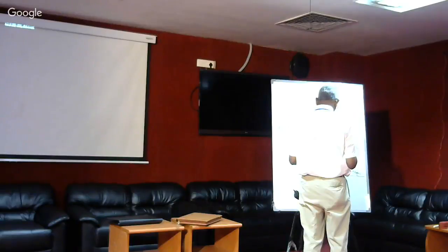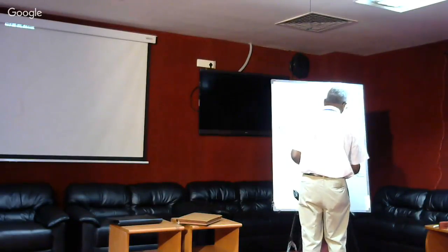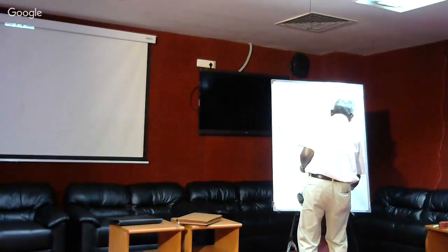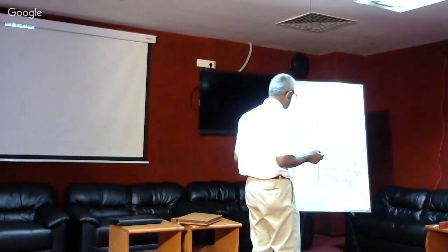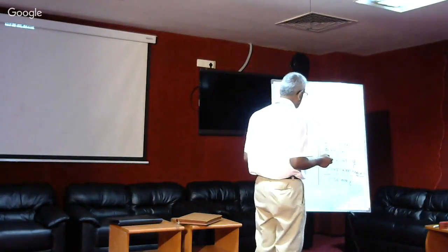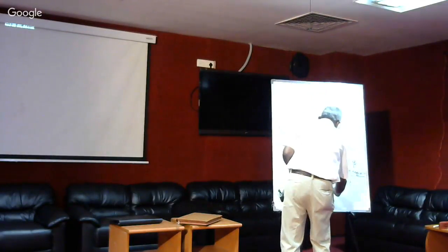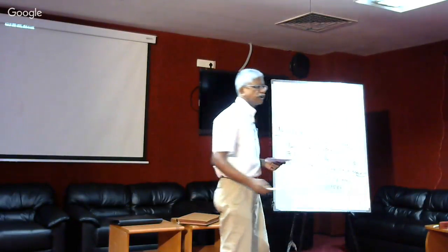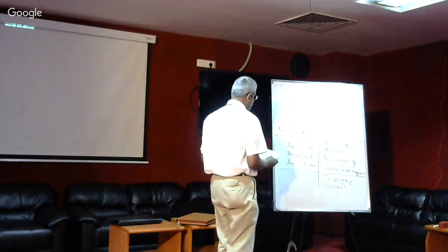The 1 liter multiplied by concentration of copper divided by Q, we will get the number of bed volumes of water treated. So this is multiplied by 1 liter actually. So liter cancels. How much volume are we treating? This is 43 divided by 0.32. 135 bed volumes. So you can treat 135 bed volumes of this water,